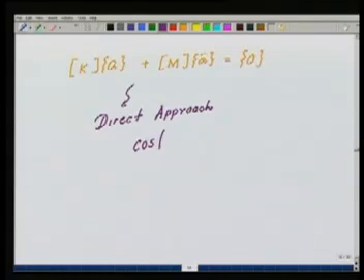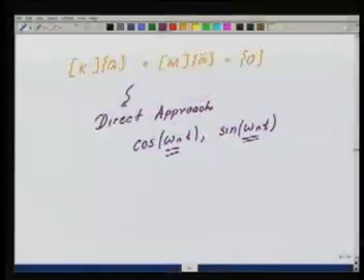This we know from our basic vibration analysis courses. Okay, then I should be able to resolve in time all the frequency components, because my solution in time is going to be cosine omega n t and sine omega n t. Okay, now depending on the highest frequency term which is there, I should be choosing the time step such that this is also resolved. Okay, so with this we will finish the temporal part of our approximation.